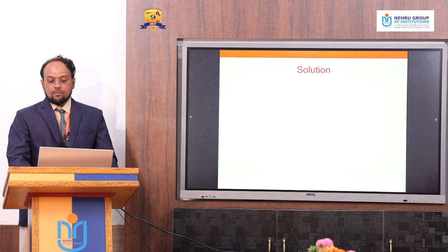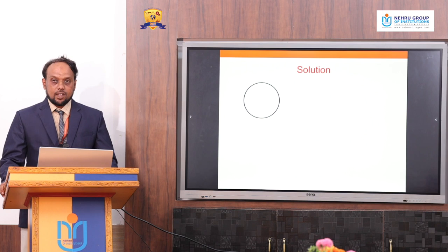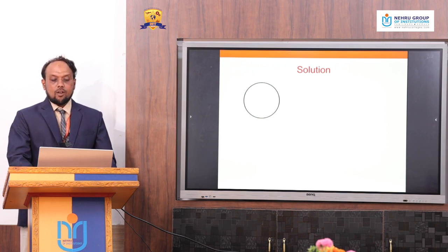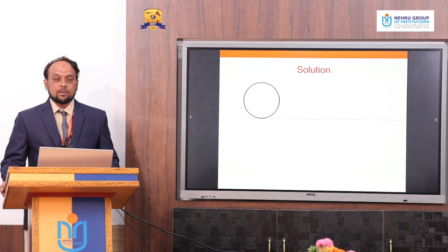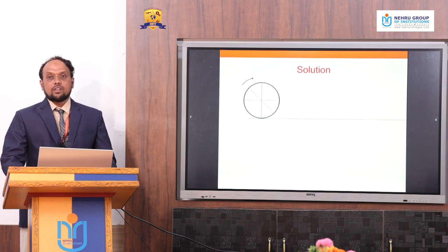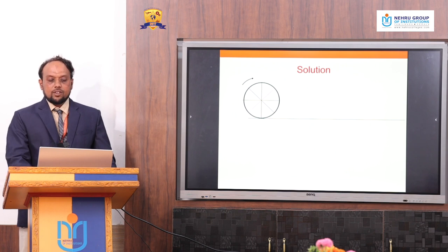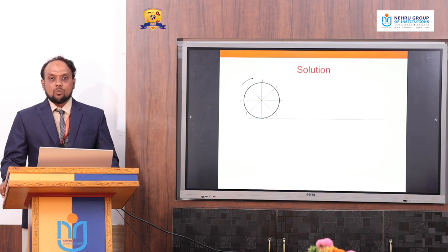Now we will go to the problem. The very first thing we have to do is draw a circle according to the given diameter in the problem. So, for example, if it is 40 mm diameter, we need to draw a circle, and next we have to draw a straight line touching the circle at the bottom, or we can say tangent to the circle. This line measurement can be calculated from the formula pi into d, which is nothing but the circumference of the circle. Next, we are going to divide the circle into 8 equal parts. The reason for dividing into 8 equal parts is that we get more points so that the curve joining will be very smooth and clear. Name the points in the anti-clockwise direction with numerical values, for example 1 to 8.